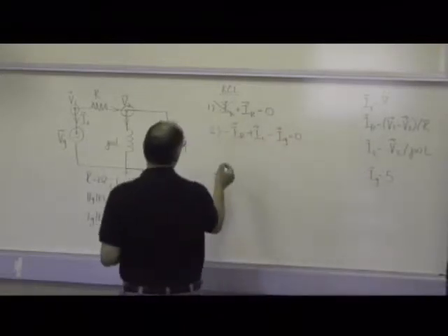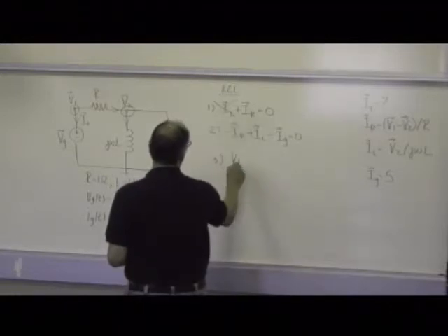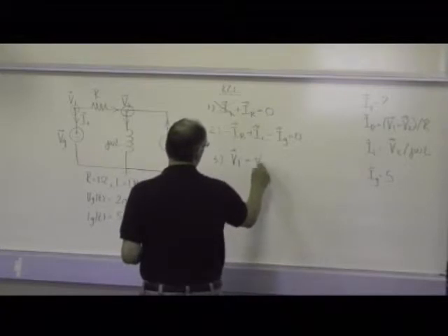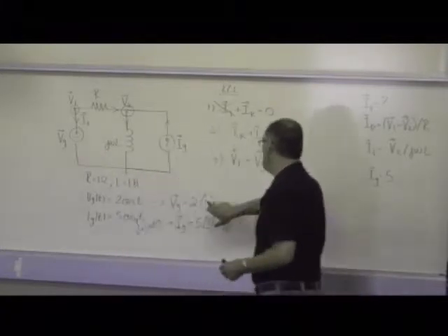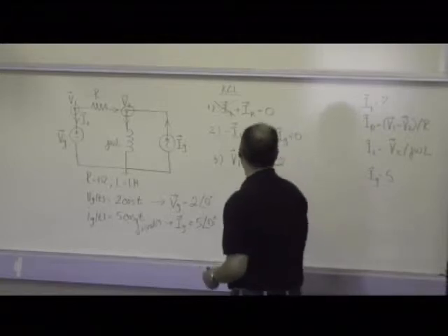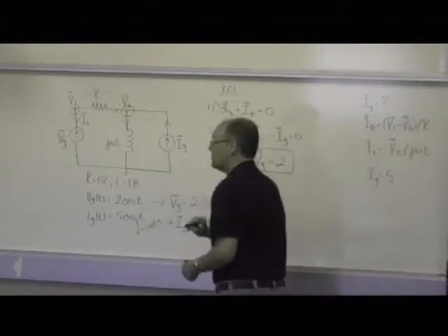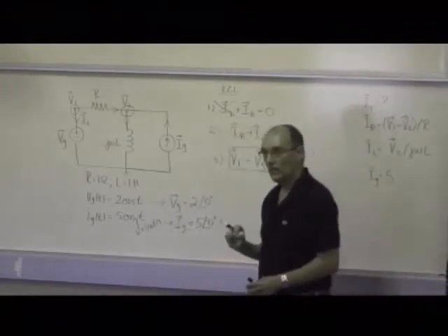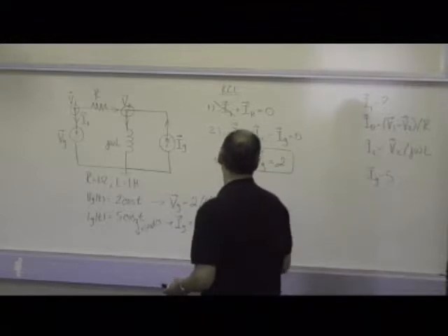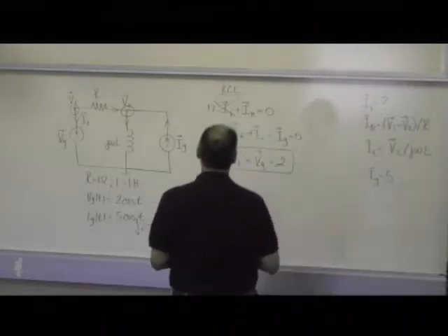And that's a legitimate replacement for this first equation. So you can say V1 equals Vg, and phasor Vg is a 2. That's a perfectly legitimate equation involving one of the nodal voltages. It's a trivial one because that voltage happens to be 2, but it's an easy equation. There's nothing wrong with it.